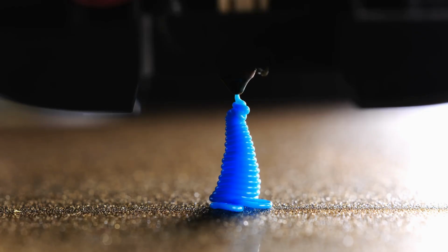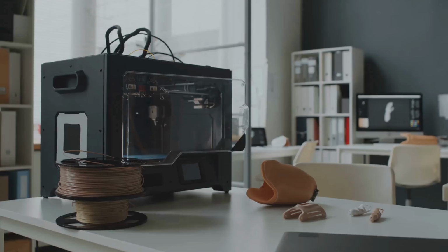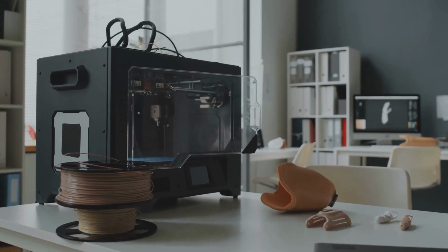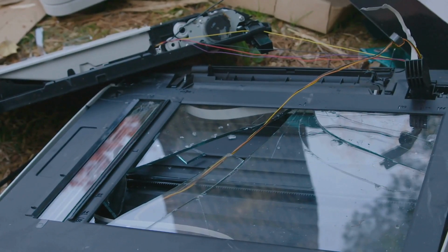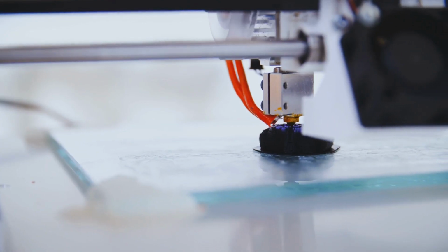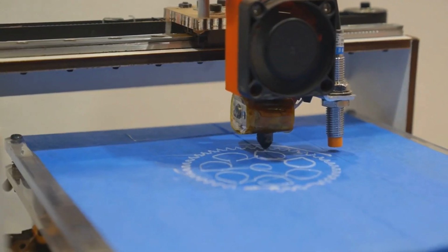Check for blockages in the nozzle. Ensure the extruder is heated to the correct temperature for your filament, and verify that the filament is loaded and feeding properly. Poor layer adhesion. This can result in prints that easily break apart. Ensure the bed is leveled correctly, the bed temperature is appropriate for your filament, and consider using a build surface